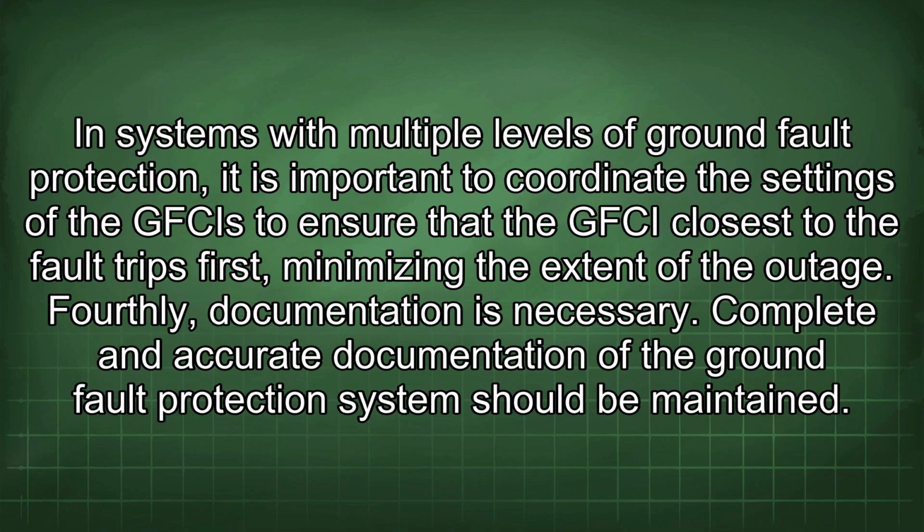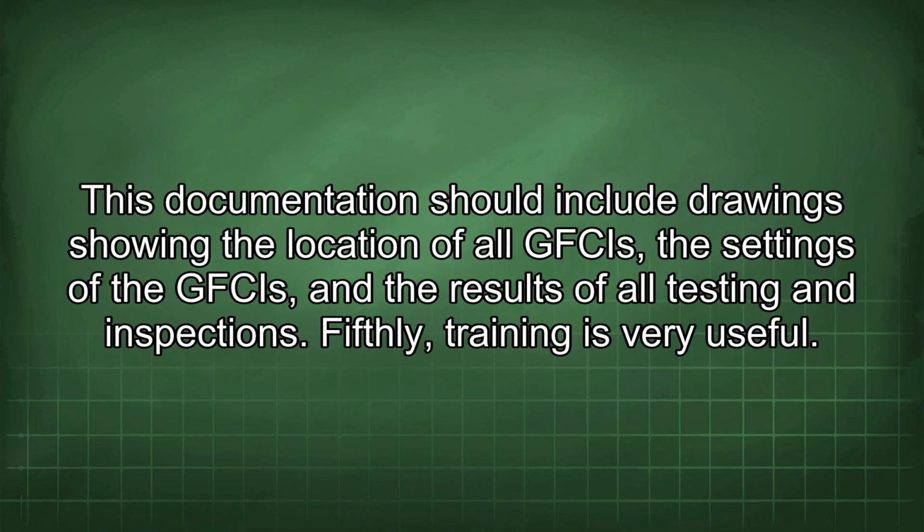Fourthly, documentation is necessary. Complete and accurate documentation of the ground fault protection system should be maintained. This documentation should include drawings showing the location of all GFCIs, the settings of the GFCIs, and the results of all testing and inspections. Fifthly, training is very useful.